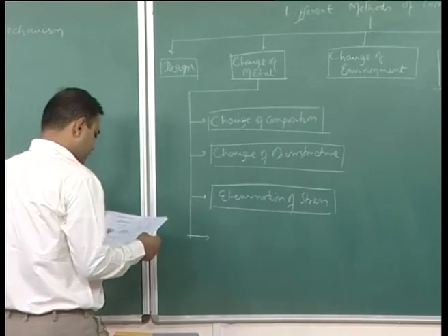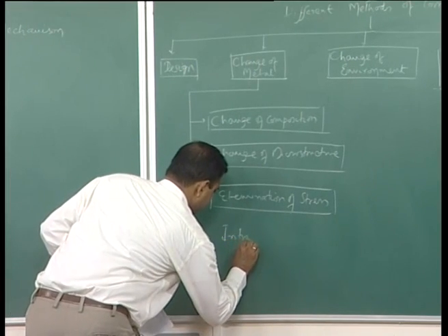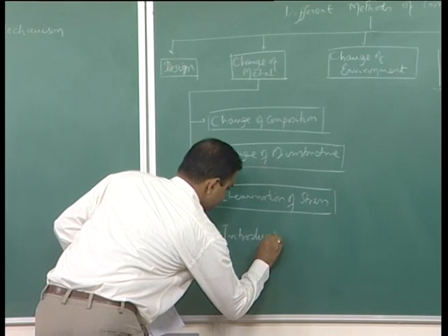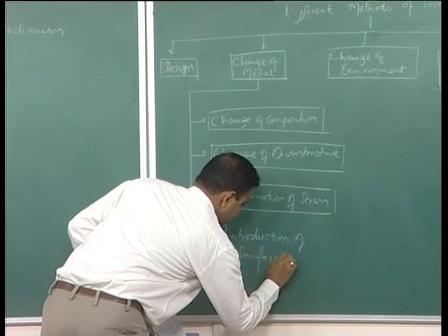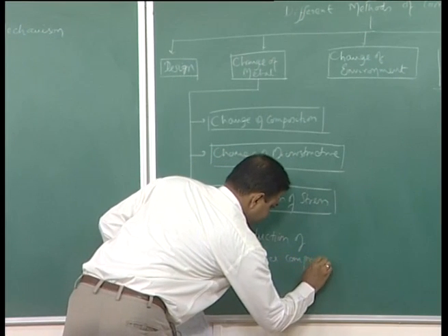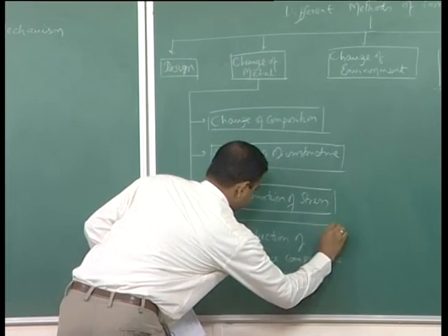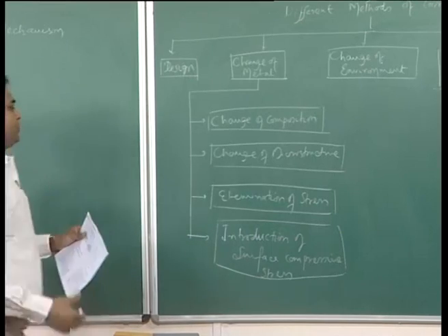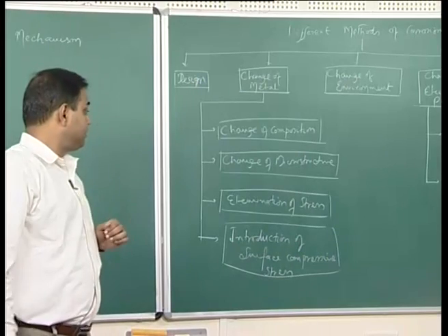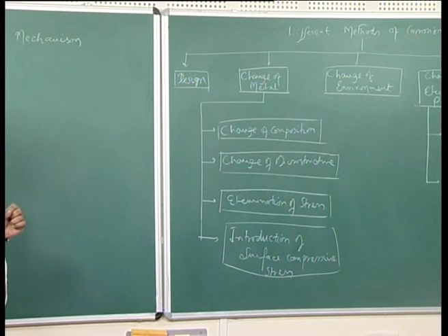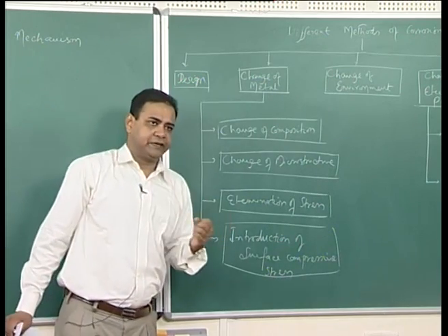And then you have introduction of surface compressive stress. So, this is one more way. If we introduce surface compressive stress, then it would have inherent resistance against fatigue.